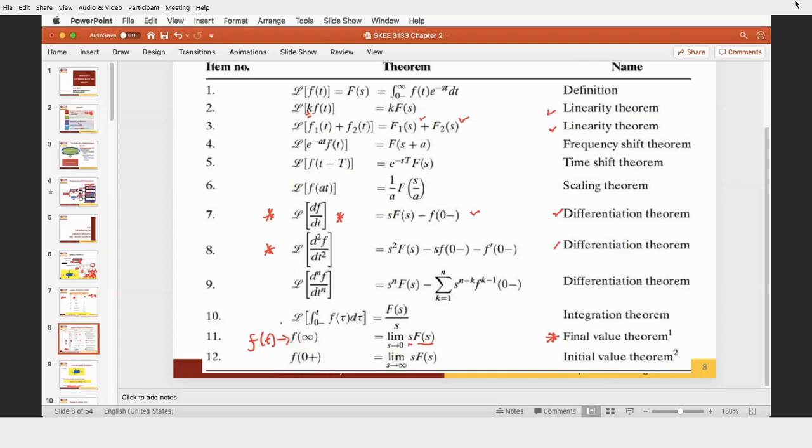F(s) comes from f(t), you Laplace it to become F(s), and you can put s at the beginning and substitute s to 0. So you can get the final value of the system when t is at infinity. When t is at infinity, we know the accuracy of the system. What is the final value of the system at t infinity? So we can compare with the set point, the set value. Okay, so finally we can identify the accuracy of the system, or we can calculate the steady state error. We call that steady state error.